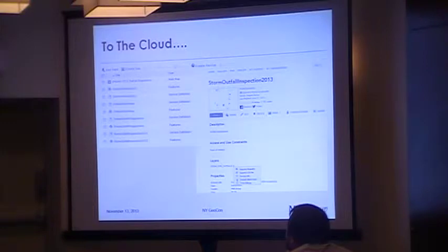So here's what the data looks like when it is in the ArcGIS cloud, just different layers in your organizational data. They're feature services. And up at the top there is our map, which is kind of like an MXD file, only in the cloud. So that map is what you consume when you open it in the mobile application. When you click on one of those feature services, and this one's the storm outfall inspections, there's a little drop down right there, and a little button that says enable or disable attachments. So that's where you go to enable attachments.